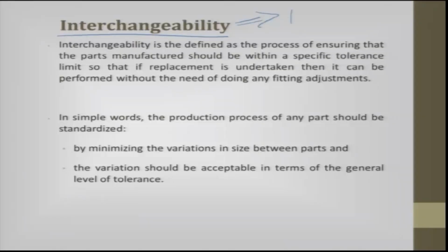So, this particular plunger and this particular barrel alone can mate, the others cannot. Basically, you specify certain tolerance such that when the parts are interchanged they can still work. And this concept is very important when we talk about design for manufacturing.